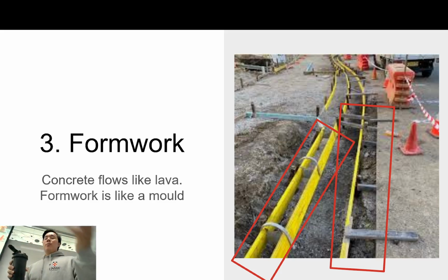Now, in terms of approvals, you need to make sure that you have your formwork approved by the client before you actually pour the concrete, right? Because if you imagine, you can change the formwork, but once the concrete's in, it's going to be a big process to be able to change that, right? Sometimes mistakes do happen and you have to break the whole thing and redo it, okay? And that actually comes out of pocket for the contractor. So if you make a mistake, that's on you, okay? So you need to make sure that you read the specs properly and you make sure that you have allowance for mistakes and things.